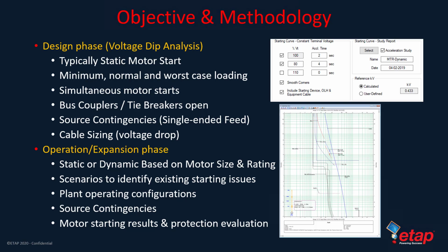For the design phase, we would be modeling typical starting motor, minimum, normal, and worst case loading, simultaneously starting motors at the same time, source contingency, so single-ended feed versus parallel, and also using that information for cable sizing.